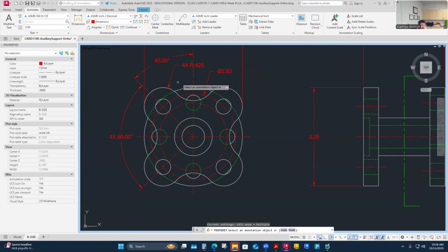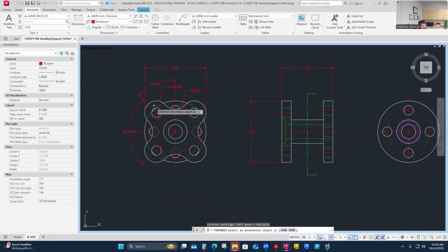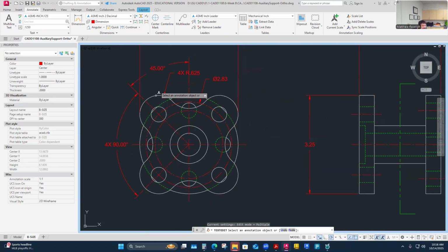It's really critical that I control here, and then I can go ahead and take this pattern around. Once I've done 45 degrees once, I can go 4 times. That'd be 1, 2, 3, 4, back to where I started. That's great. There are other ways I could do this. So that is locating. It's going to come in handy. These are going to be some of the same locating dimensions for the center, for the little hole. So it's probably going to do double duty a lot. Even the bolt circle is going to do double duty on that.